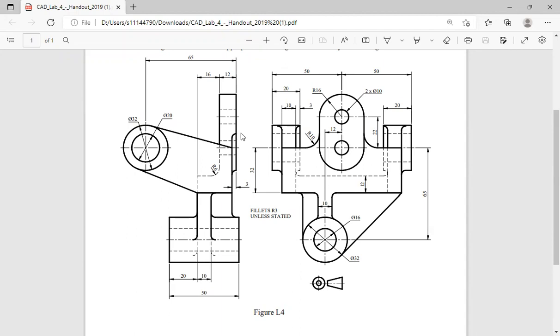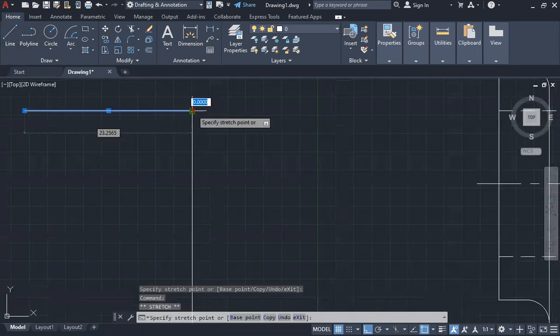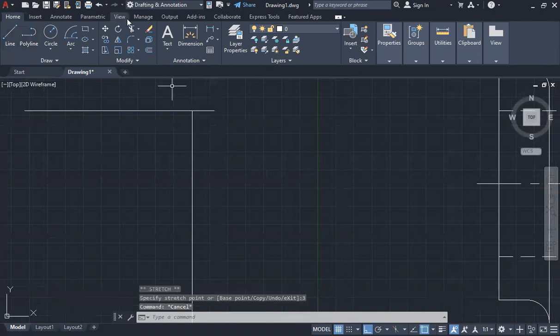So this fillet here corresponds with where this radius 10 fillet touches our slot. So what I'm going to do is first draw a line from this point across, and then a line from this point to touch that line, extend it by 3 mm and then just trim away this stuff. Okay.